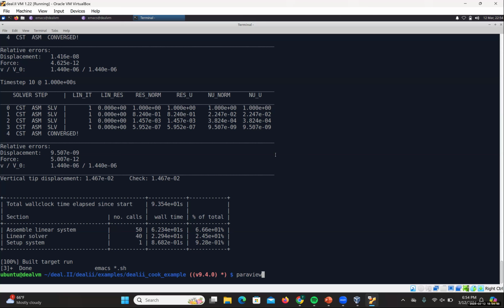Oh, another thing I want to highlight for this example is this little printout of the total displacement of the vertical tip of the problem. So you can do whatever post-processing you want in deal.II in the C++ program. There's a line that says, okay, for this node, extract the displacement at the last time step and print it out. Maybe you have this parameter file, you're changing material properties, optimizing over a bunch of runs, and then whatever metric you care about, you print that out too. That's the good thing about deal.II: it's very automatable and flexible to however you want to do things.